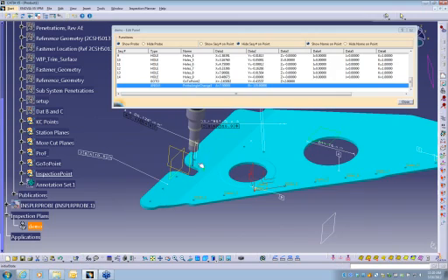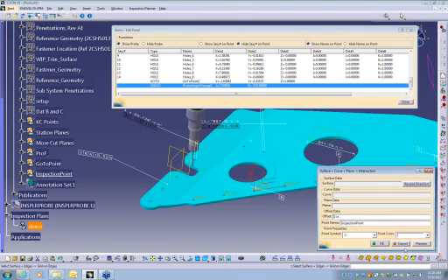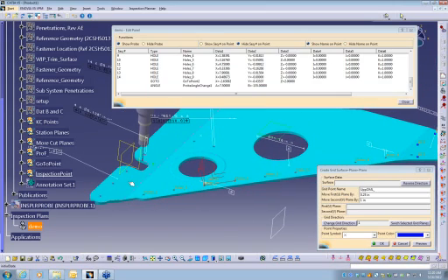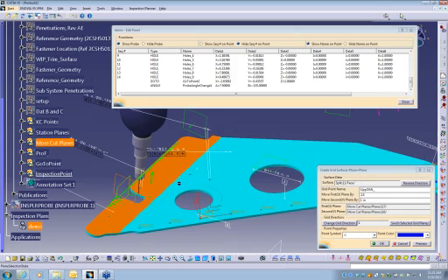And now we're gonna measure this surface right here, and we're gonna utilize these 2 planes for a gridding function. So we can come in here and say I want to perform, this is the wrong icon, I'm sorry. Let's say we want to do a 150 thousandths grid one way, and a 1 inch grid the other way, and we give this a name, upper OML. We can pick the surface, we can set the vector. So our 0.15, we want to go from this plane, and our 1 inch, we want to go from this plane, and we have 4 different starting quadrants that we can go through.